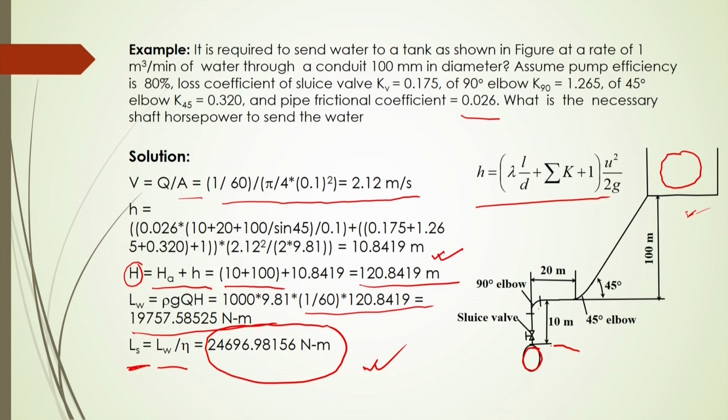and those minor losses arise if you are using different valves, bends, elbows or different cross sections, by changing the pipe and changing the directions. Then you have to use this equation for total energy loss calculation.